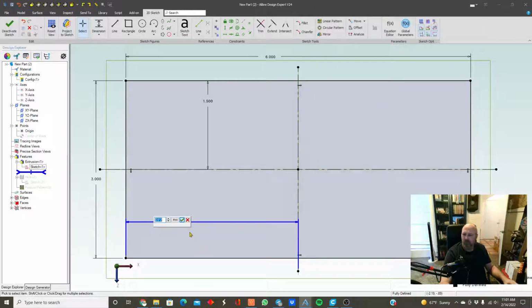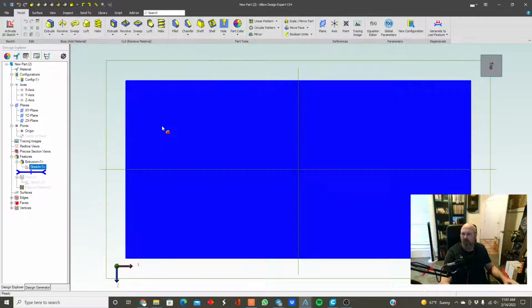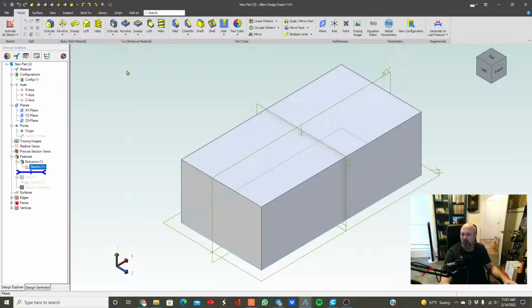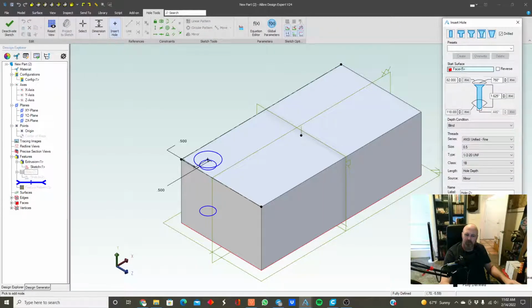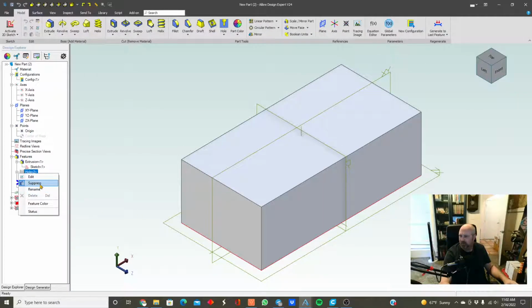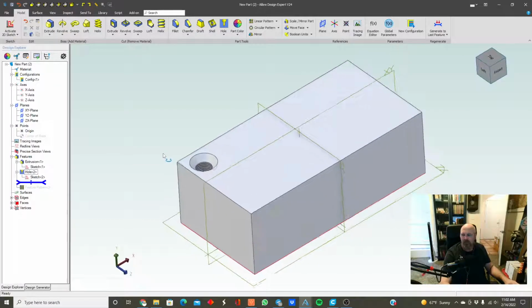Okay, cancel. Okay, just save all that stuff out. So what I wanted to do, deactivate it. Let's go into our 3D view. You can actually preset this, so every time you deactivate it, it'll rotate the part. And I kind of like that. I use that at work. This is my home unit. So generate the last feature. So I've got it all grayed out. So right now, go through edit. Oh, let me unsuppress it. Okay. So now what it is, this is our hole.